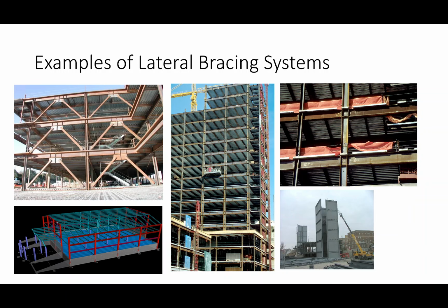So brace frames are the most common, and then there's also moment frames. If brace frames are like trusses in CE 312, these are like frames in CE 312. Remember, the difference between a truss and a frame is that a frame can withstand moment. From a design standpoint, moment frames are more open. You don't have big braces in the middle of the window. They do tend to be a little bit more expensive. You would think this would be because of the big members, but what makes moment frames more expensive are the connections. You have these really complicated connections and you have to use a lot of them, so they rack up price pretty quickly.